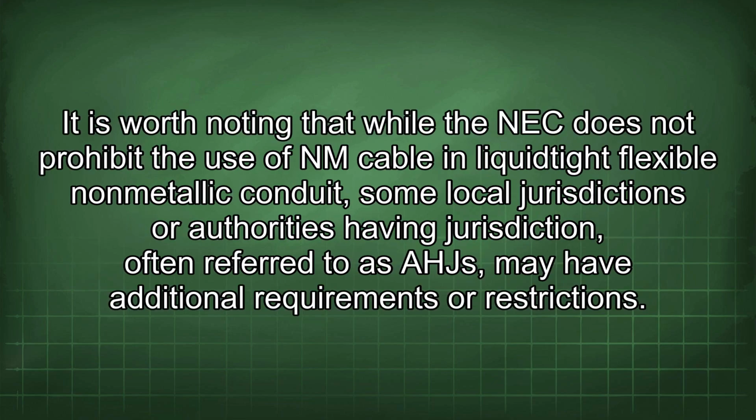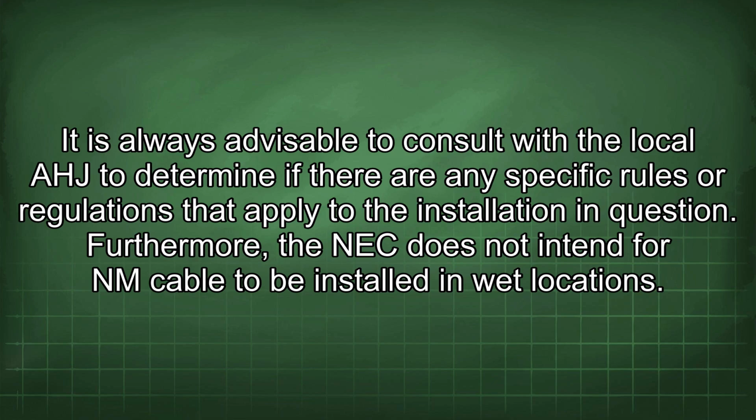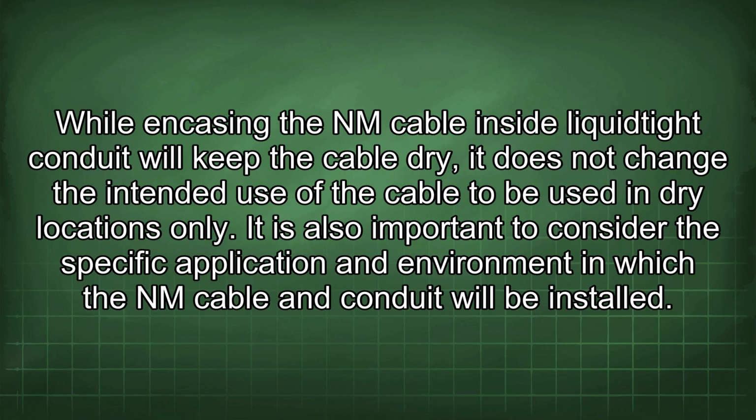It is worth noting that while the NEC does not prohibit the use of NM cable and liquidtight flexible nonmetallic conduit, some local jurisdictions or authorities having jurisdiction, often referred to as AHJ, may have additional requirements or restrictions. It is always advisable to consult with the local AHJ to determine if there are any specific rules or regulations that apply to the installation in question. Furthermore, the NEC does not intend for NM cable to be installed in wet locations. While encasing the NM cable inside liquidtight conduit will keep the cable dry, it does not change the intended use of the cable to be used in dry locations only.